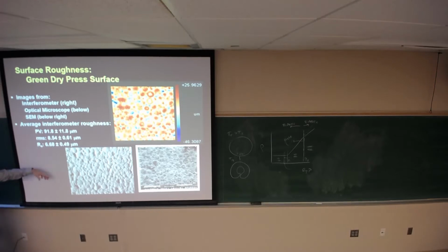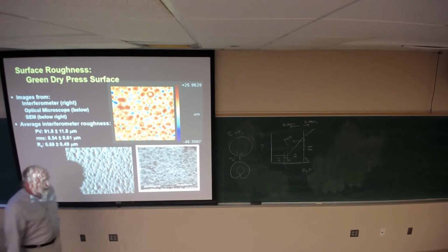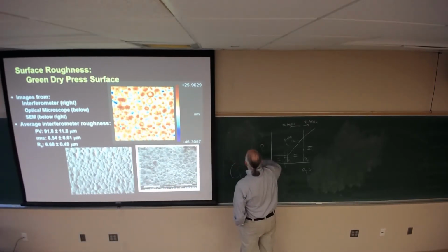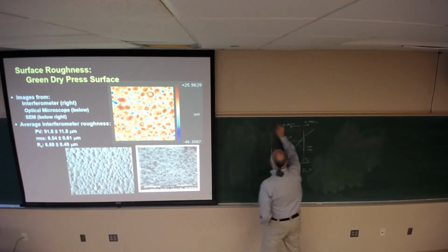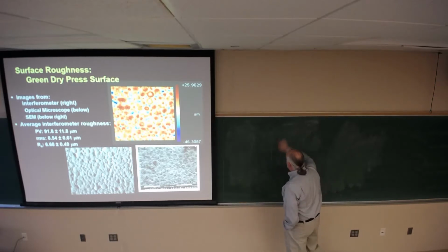So you get dry press behavior, and you can see in this optical image granules that are still present. So by pressing, we now have what are called semi-isostatic dies. Semi-isostatic dies for dry pressing are very common now.